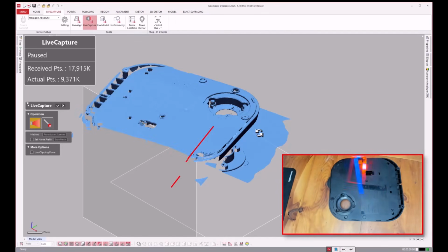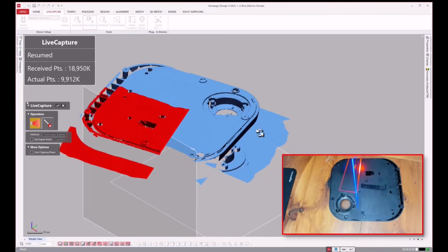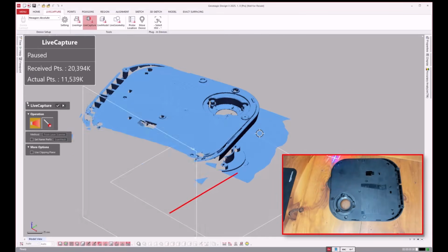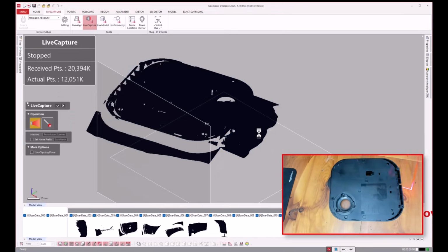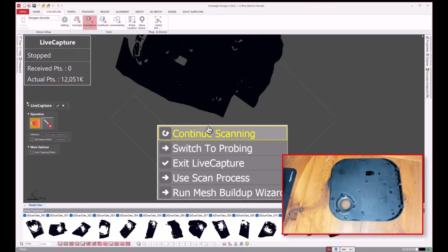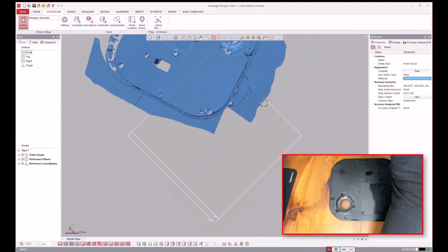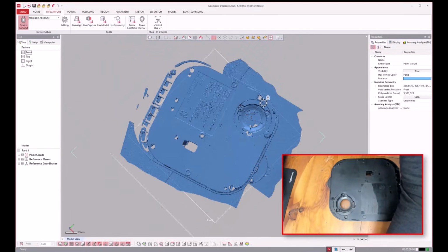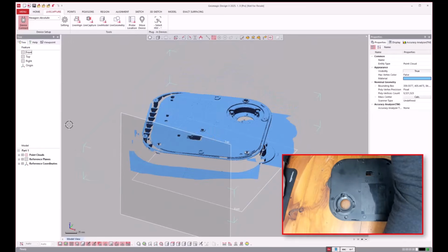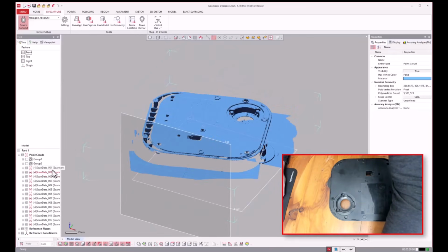So you can see here, I'm over scanning too. I needed the cavity, I didn't need the whole back side, but sometimes it only takes a minute to scan a little extra to help use that for alignment purposes to piece those components together. So then we get out of the plugin again, group the scans, and rinse and repeat over and over again. This is how you would do a more elaborate project versus just scanning a part, flipping it over, and scanning again.